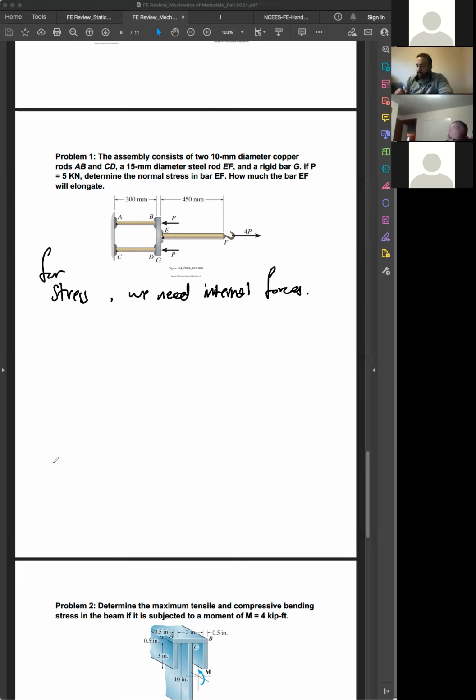All right. So internal forces, how can they be found? By cutting the member. So we need to cut the member and look inside, and derive and find the internal force using the equilibrium equation, right? So if the member EF is requested from me, I know that I need to cut it. I need to cut and look inside the member.